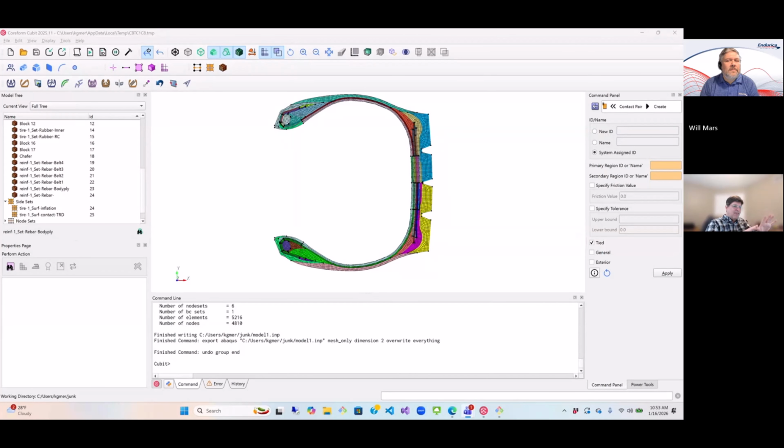When we have these wavy sipes, the meshing is actually not a problem if they're all going down to the same layer. If they have different depths at the bottom of the sipe, then you have to find ways to cut those up and decompose that in a way that you can define that many-to-one kind of mesh.